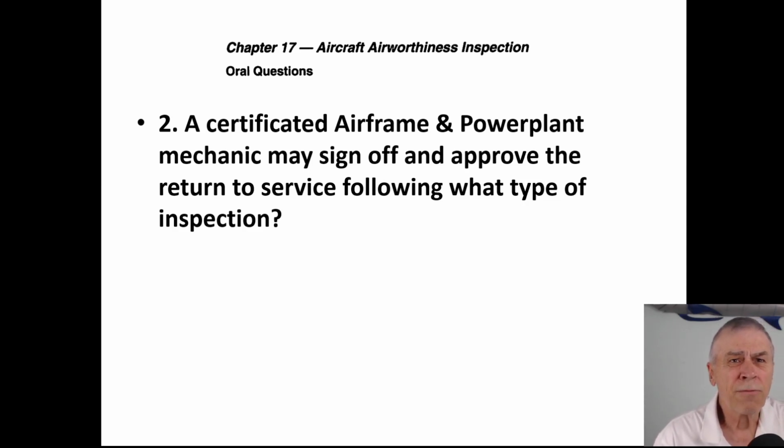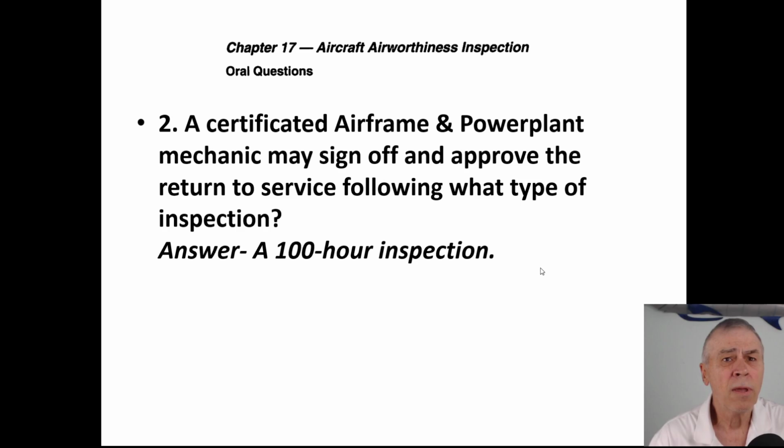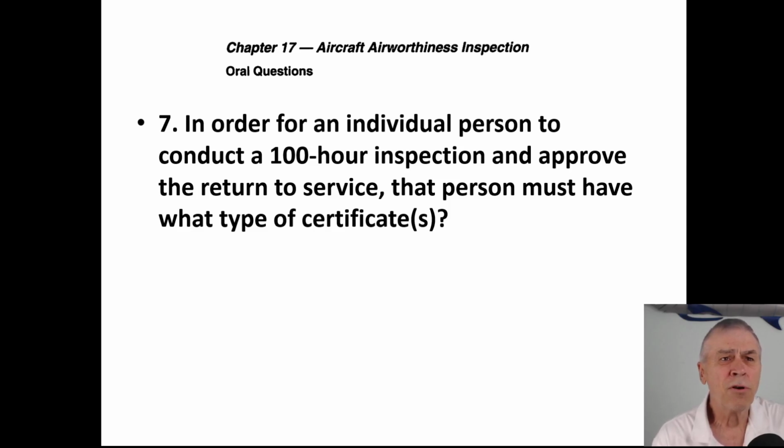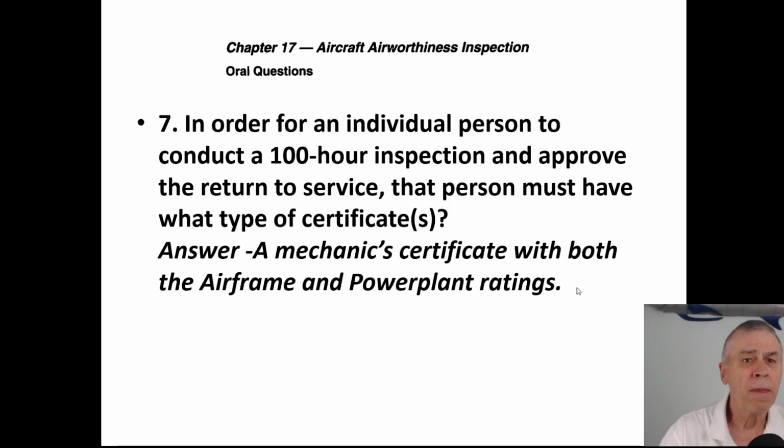A certificated airframe and power plant mechanic may sign off and approve the return to service following what type of inspection? That would be the 100-hour inspection. In order for an individual person to conduct a 100-hour inspection and approve the return to service, that person must have what type of certificate or certificates? Well, that would be the airframe and power plant certificates. I guess the more proper way is to refer to your mechanic certificate. It's the same ID card, but on the back it'll have your ratings, and airframe and power plant are the two ratings.